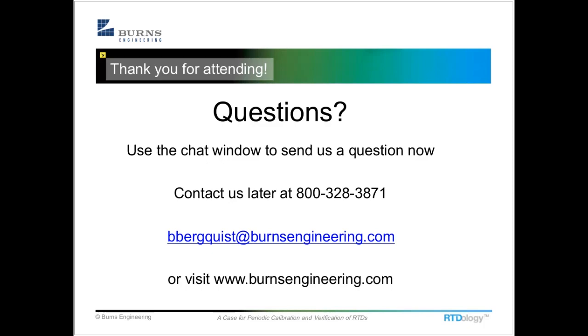If you have a temperature point that's not measuring correctly and you just turn a dial to turn the temperature up a little bit so you get some kind of output that you like, that's really probably not the best way to handle that. So doing that initial verification check, just to ensure that things were installed and are working correctly, can go a long way towards making that process run a lot more smoothly and ending up with a good quality product in the end.